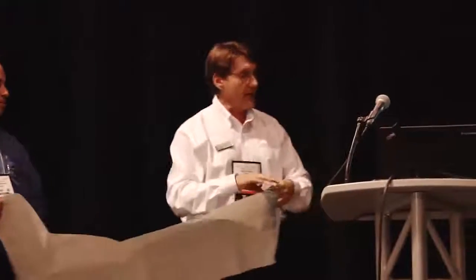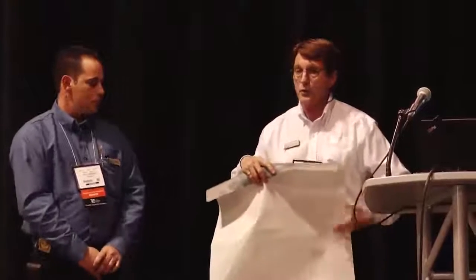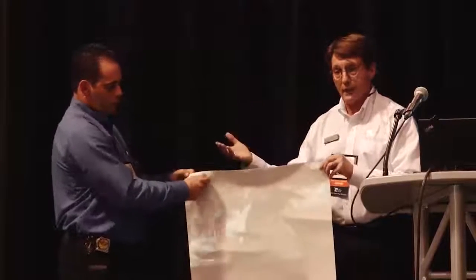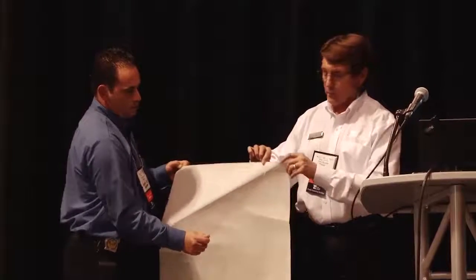What we're going to do for the next part of this presentation is that my colleague here, John, is going to run through some very basic steps on how these materials are to be installed. To start off with, membranes come 3 feet wide by 100 feet long in a roll. The contractor can easily clip it off to a manageable size. And what John and I would like to show you here is that there is a proper way of pulling the release film off. And it is typically a 2-man job just for its sticky material.